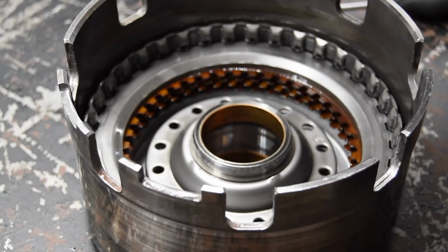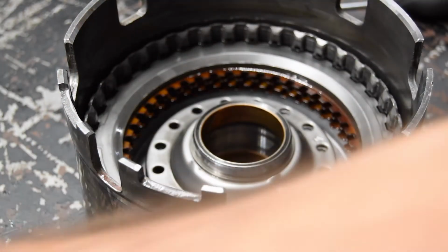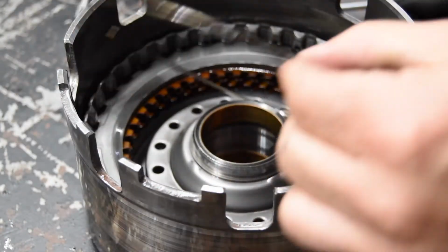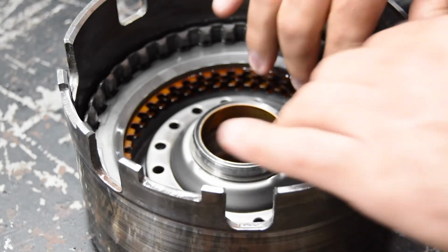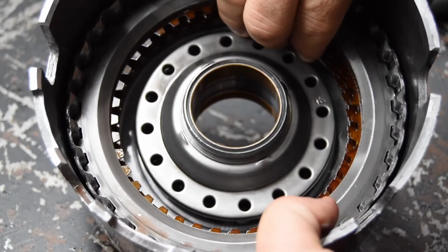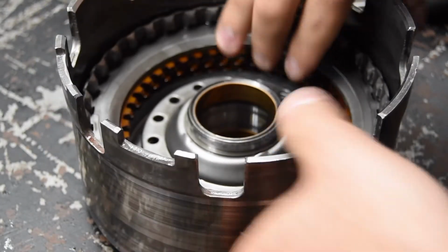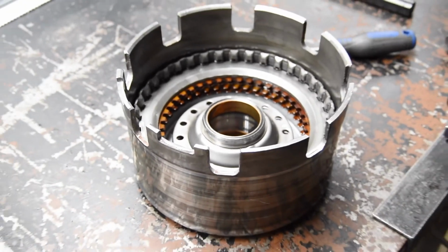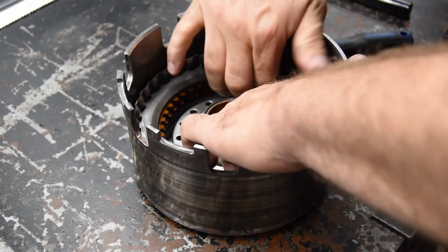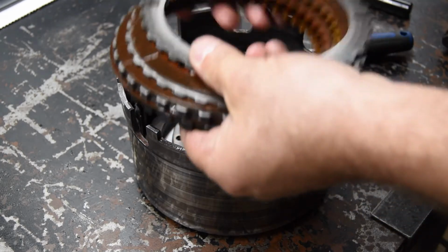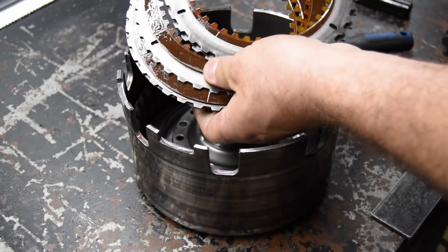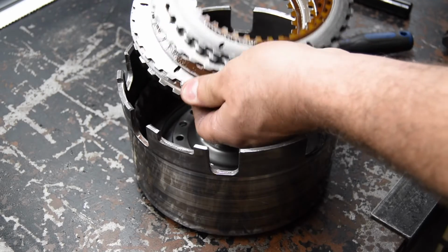Now the snap rings in most transmissions are going to be clutch specific because the diameter and then the thickness is going to be specific for this clutch drum and clutches. Now from there, all I need to do is just lift up on the clutch plates and then pull them up and out of the clutch drum. So the first thing you want to do is pull the clutches out, and you want to flip them over, and you're going to just take a look at the general condition of these things.